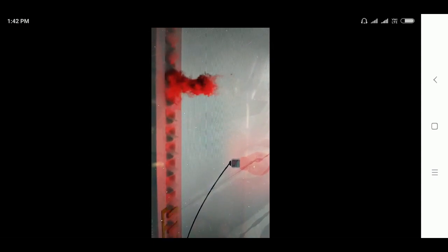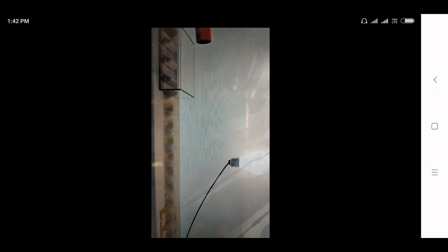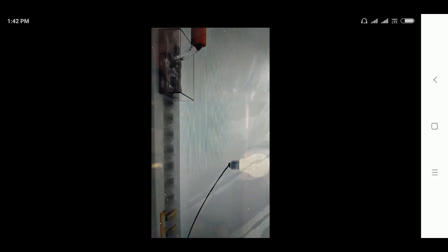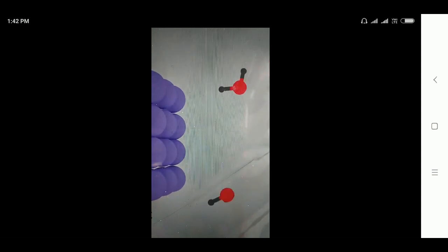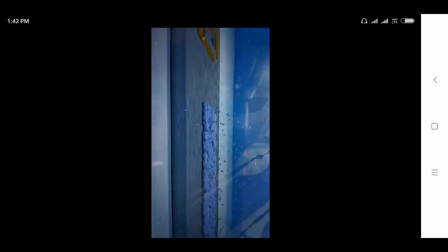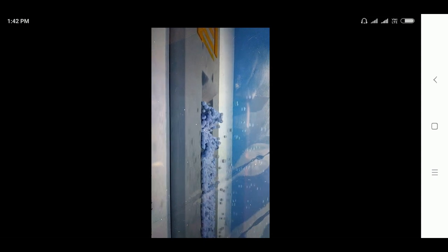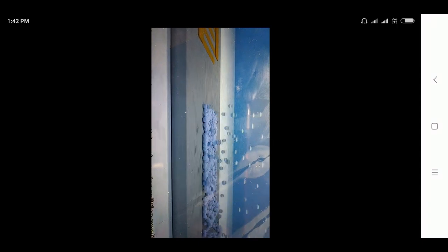Say if it encounters a gas in its path, different gases will have different effects. We can add some liquid in the path of the SAW. We can see that this reduces the energy of the wave at the receiver. This means that the energy is transferred to the water molecules. A combination of this energy and titanium nanoparticles can be used to split water into hydrogen and oxygen. Hydrogen generation is increased exponentially, which can be viewed in this video.